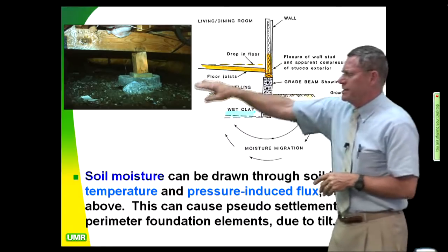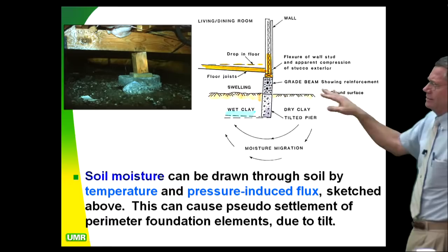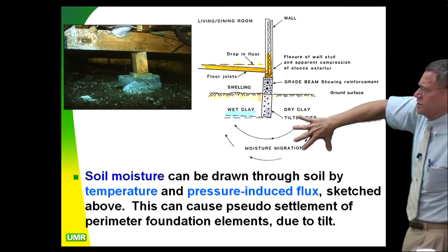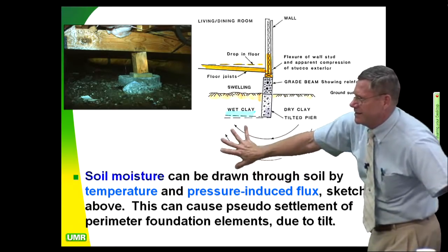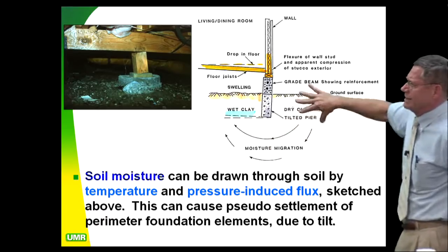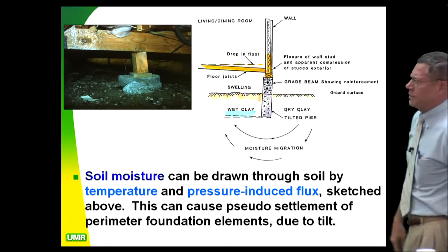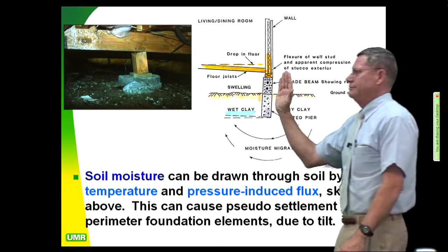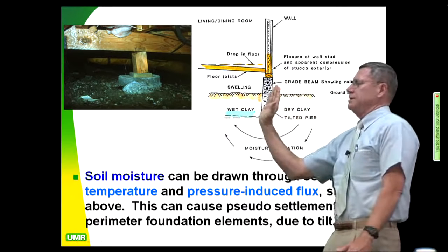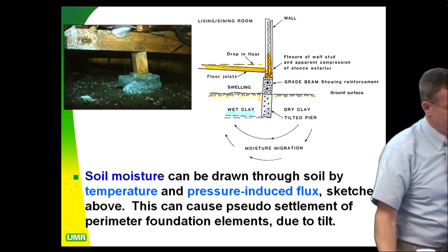What's going on? Well, if you look at a cross-section in this area, they had a very, very wet area out here, and then they let it go dry and desiccate. And they had these little stub piers that are only about 30 inches deep, connected to a grade beam. And as this dries out, there's actually a moisture suction effect going like this underneath, because this is all dry, so it's pulling the water out of there through suction and causing an over-consolidated clay condition, and so the ground started sinking. And this lady had 3.5 inches of settlement in about a 6-week period. She'd lived there the whole time. And then here you also have a tilt, and the tilt is because of the progression of the drying front. So you're wetter over here, drier over there, so you actually get a tilt going like that. Anyway, this should scare you. This is not a good situation at all for lateral loading in a quake.